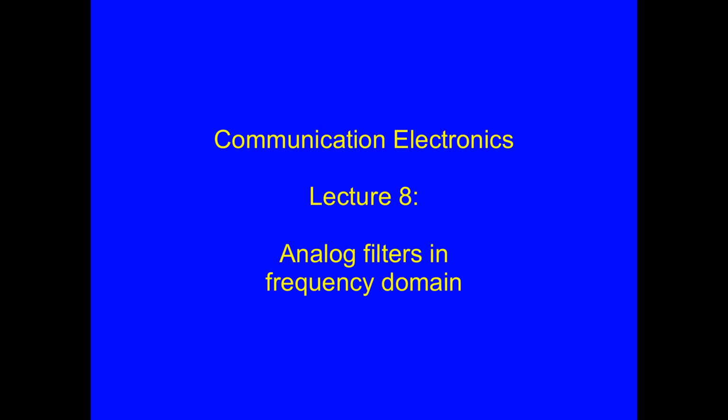Why are filters in frequency domain required? They are required to limit the noise in our receiver, to limit interference in our receiver, to limit spurious transmission out of our imperfect transmitters, and also analog filters are required in front of any analog to digital conversion, and analog filters are also required at the output of digital to analog conversions.